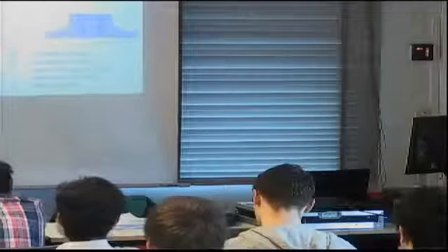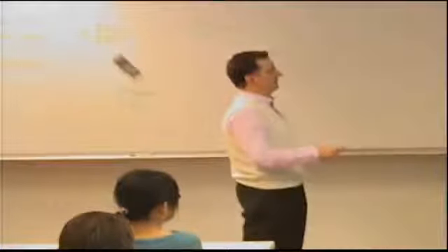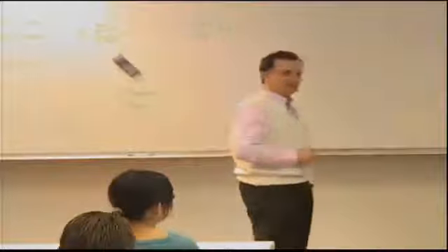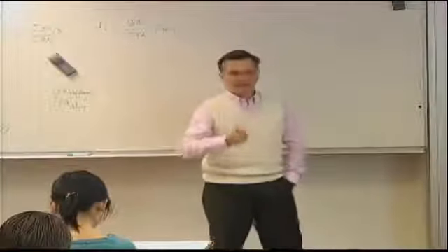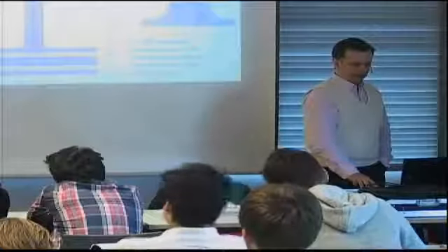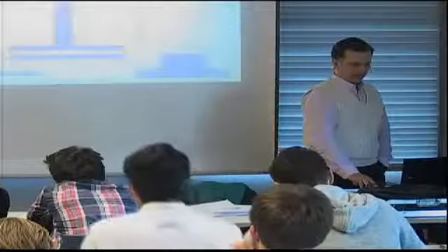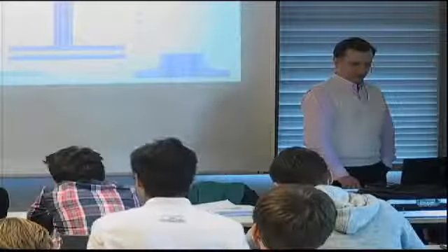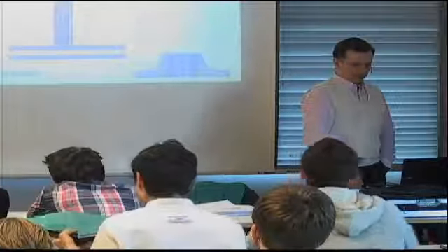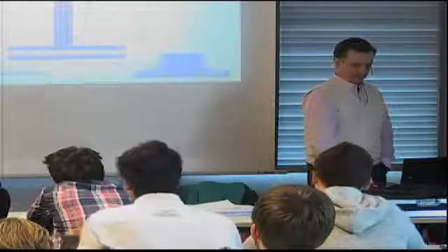If this is the skin layup we are sticking with, this is probably a problem area because of the high stiffness mismatch between the flange and the skin. Exactly what that means and how to analyze it, we will do in a couple of lectures or so. But so far, this is our next update on our stacking sequence.